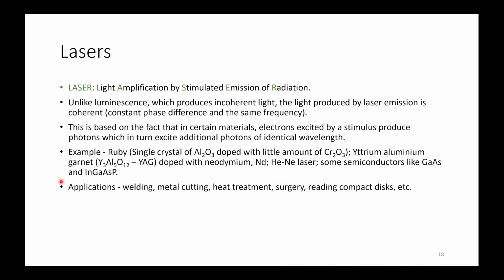Another application of optical properties is lasers. Laser is an acronym for light amplification by stimulated emission of radiation, and unlike luminescence, which produces incoherent light, the light produced by laser emission is coherent, with a constant phase difference and the same frequency. This is based on the fact that in certain materials, electrons excited by a stimulus produce photons, which in turn excite additional photons of identical wavelength.